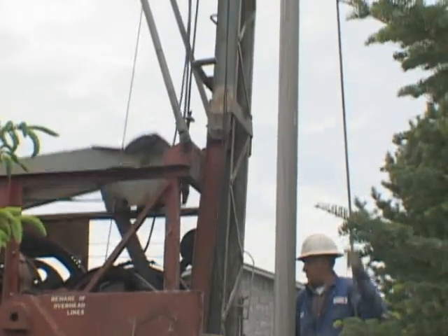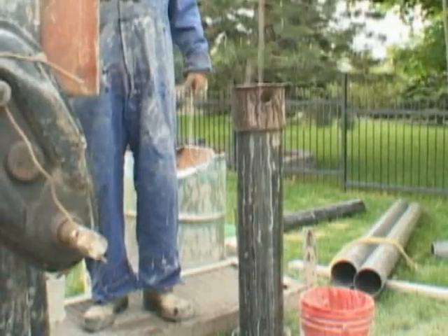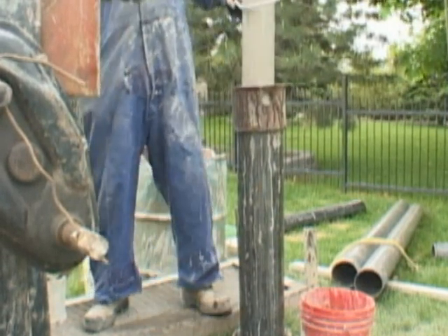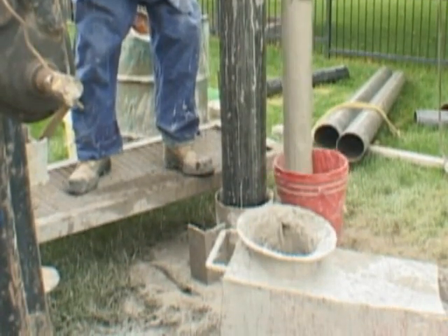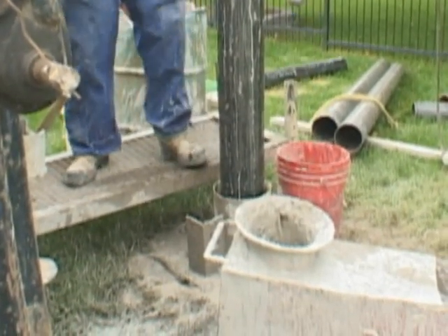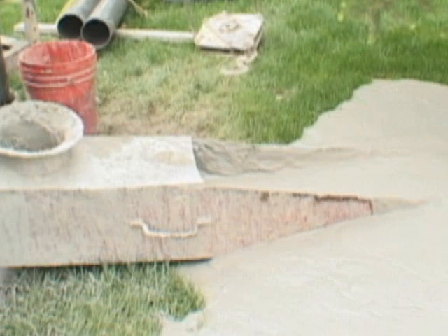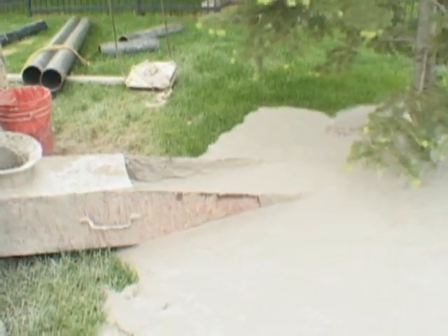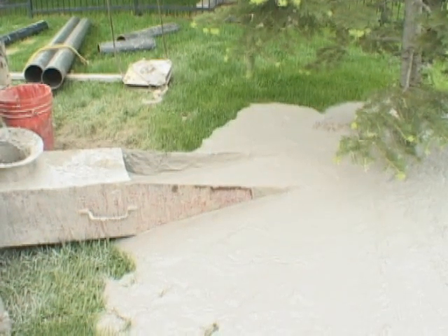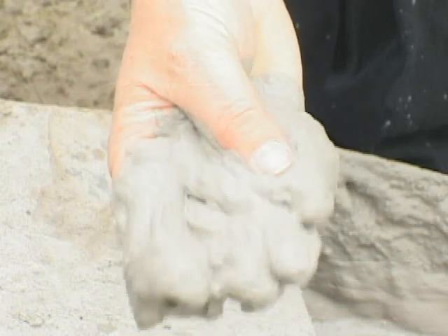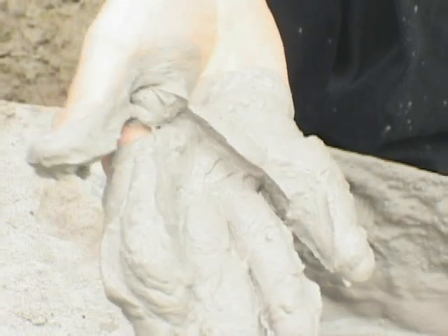This flushing system requires the drill string to be tripped out of the hole and the bailer to be tripped into the hole. The bailer is simply a hollow tube with a check valve on the bottom, which fills with the cutting slurry mixture. The action of the dart valve enables the bailer to collect cuttings for ID and recording purposes, as per Regulation 903, as well as removing accumulating cuttings by dumping them in the mud spout. The bailer is also useful for measuring approximate water pumping rates and levels at any time during the well construction. The cuttings from the borehole are usually well mixed and small in size, representing an accumulation of the formations encountered since last bail.